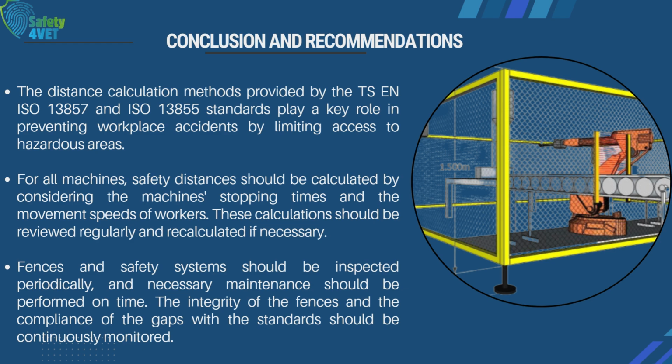Additionally, full compliance with international standards such as ISO 13857 and ISO 13855 will enhance workplace safety. It is recommended that guard fences and safety systems be periodically inspected and maintained. Finally, regular training about safety distances and the safe use of machines should be provided to workers. This training will raise awareness and help prevent accidents.